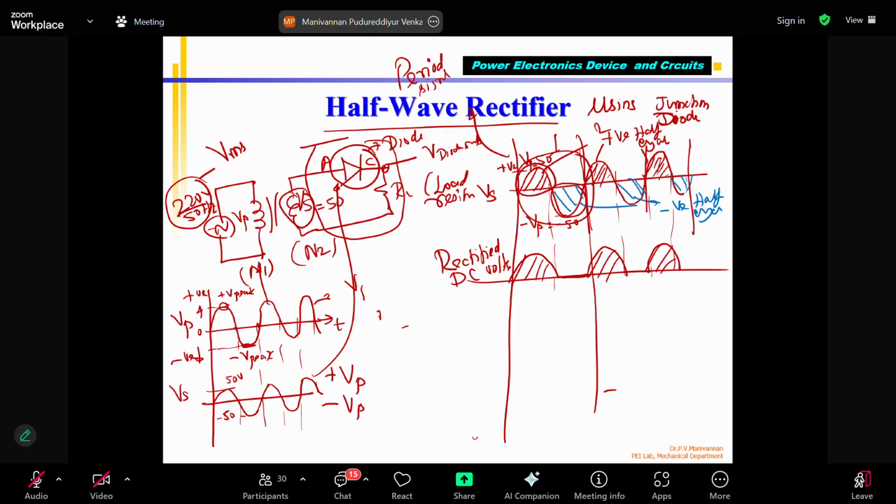Okay, if I pass my sinusoidal AC voltage into this diode, it will produce an output which is a rectified DC voltage. In fact, it is called half wave rectified. Why? The diode conducts only in one direction. When the anode is positive and the cathode is negative, then current will flow, and that also above 0.7 volts. For understanding purposes, say that if the cycle is positive, the output will pass and current will flow through this circuit. Let me remove unwanted things.